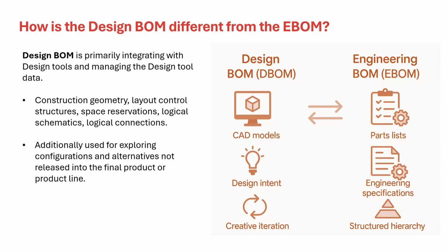So how is design BOM different from an engineering BOM? Design BOM is CAD-centric, authored by the designer in the CAD tool. It has the master of 3D geometry, CAD drawing, and models. It will have the logical semantics, logical connections, and the entire structure will be built in the CAD tool.